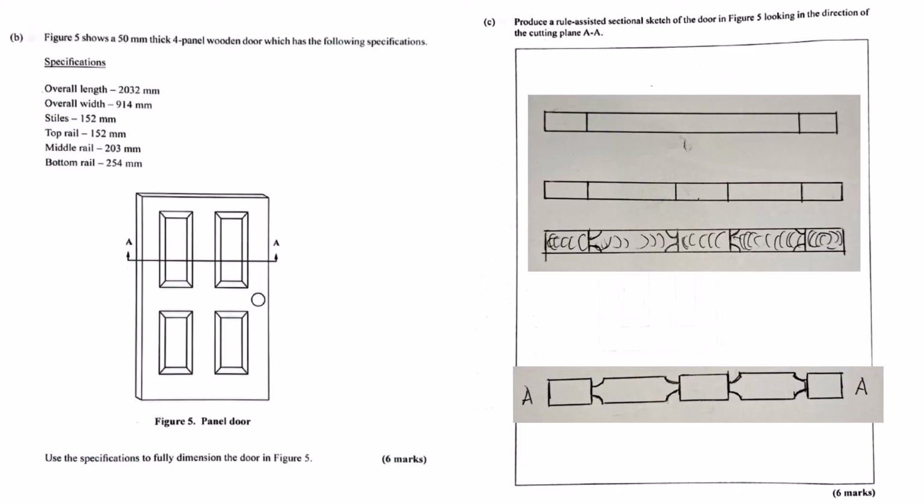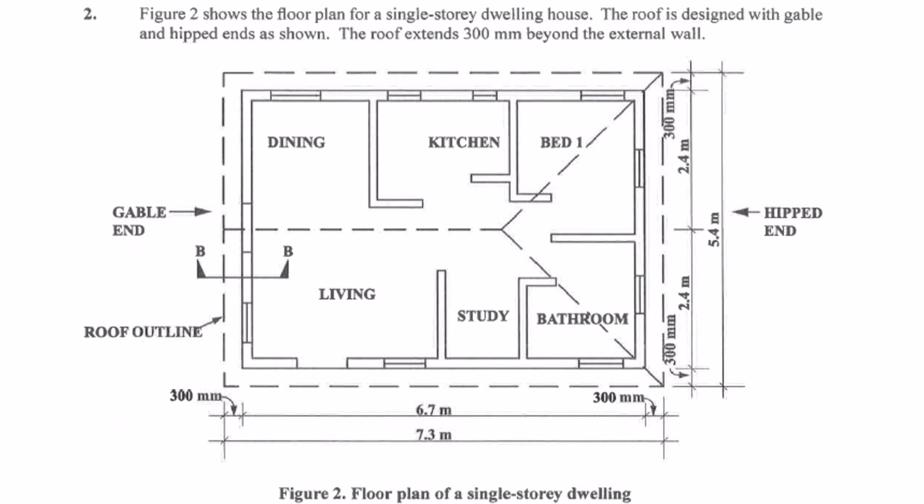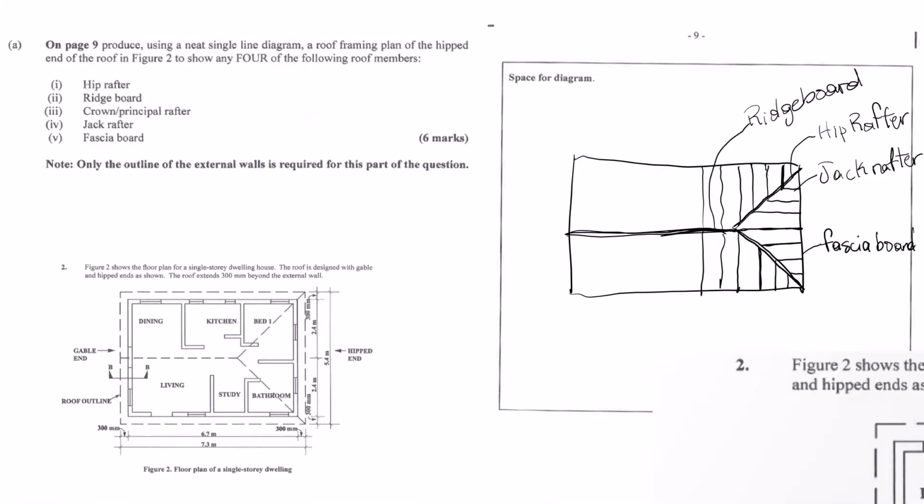Okay, let's look up at the roof now. A hipped roof, specifically. If we're looking at the framing plan from above, like a bird's eye view, what are the main bits we'd see? Right. Looking down on the framing plan for a hipped roof, you're seeing the skeleton that holds it all up. One key piece is the ridge board. Ridge board. That's the horizontal beam running along the very peak, the highest point of the roof. It's like the central spine where other rafters connect. Okay, the backbone, got it.